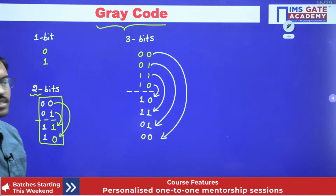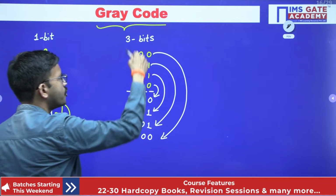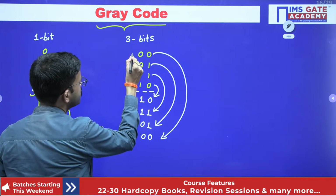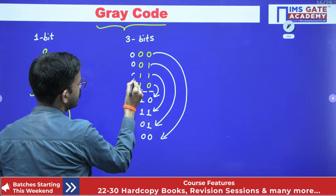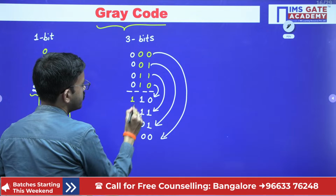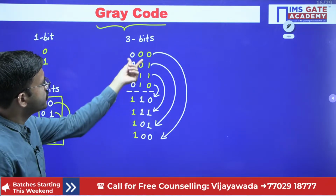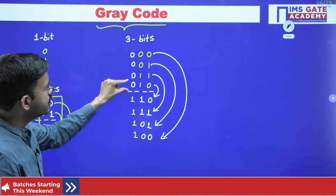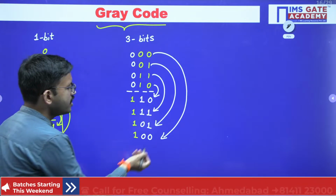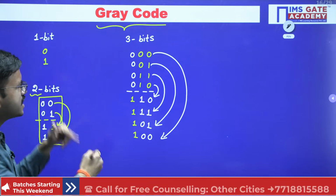Okay, right. Here if you observe, in total you are getting 8 combinations. That means the first 4 combinations you can simply put 0, and the remaining 4 combinations you can simply put 1 for the first bit. Now here also, if you observe any two successive codes, only 1 bit will differ. Even the last code and the first code differ by only 1 bit. Okay, that is a cyclic code.